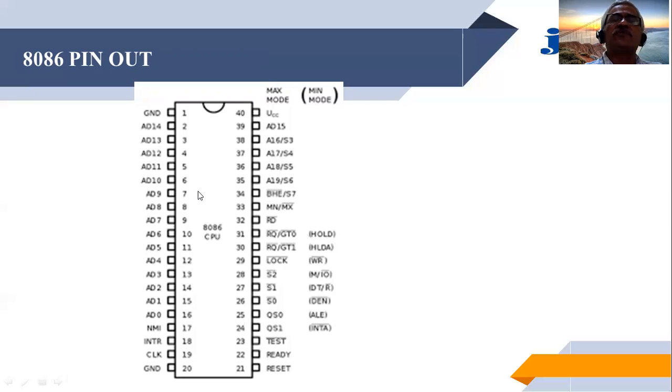Interfacing we'll see in the next video. Now we know that the 8086 doesn't have an on-chip provision; it only provides the address lines, the data lines and maybe some control lines. So we need to make use of these lines only in addressing the external memory.